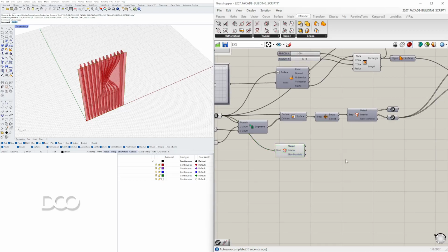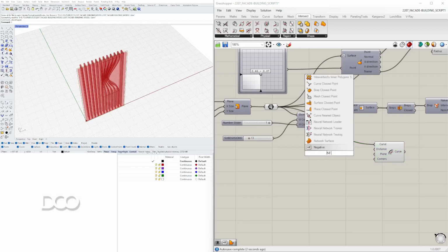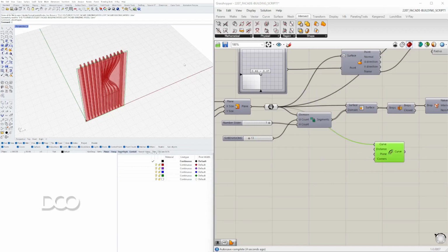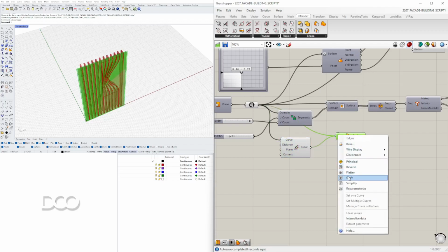So we'll go here to, well, what happens is when we have that surface, we can automatically offset it. We don't necessarily need to bring the B-rep edges. We can just offset this, and we will offset that to the outside. So I'll go here to boundary surfaces. Between these two, and then I'll flatten the input.